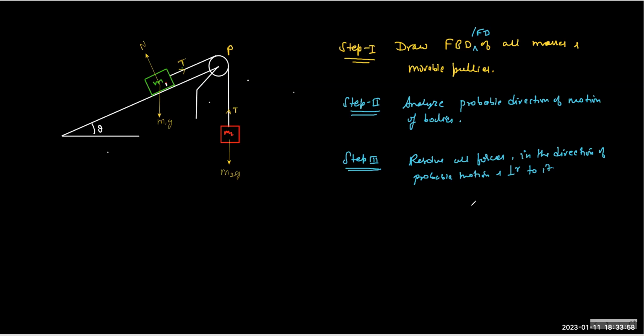No. So whenever you come across a situation where the forces are neither parallel nor perpendicular, there we do the resolution of force, just like a resolution of vector. So we can draw a line like this. And definitely you can see the M1G is in this quadrant. The first step in resolving any vector is that we need to know the angle first. If you assume this as theta, this will be how much? So this will be 90 minus theta. Understood?